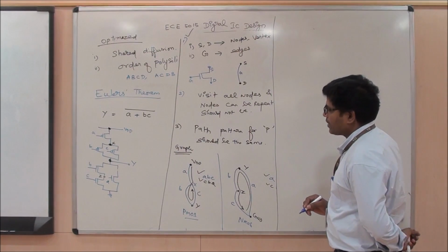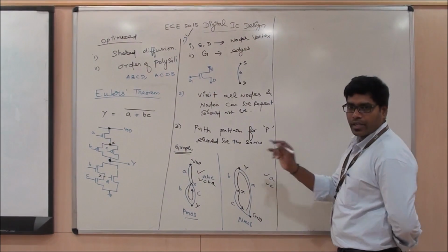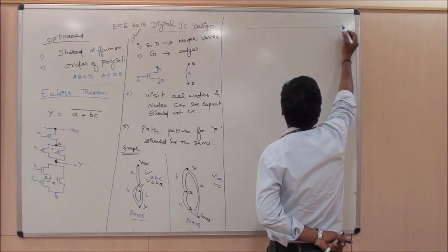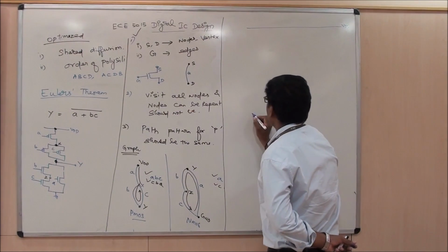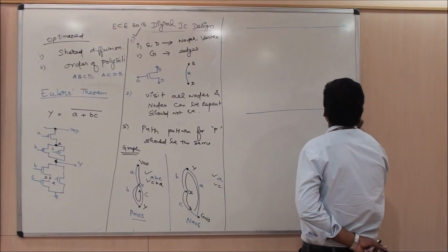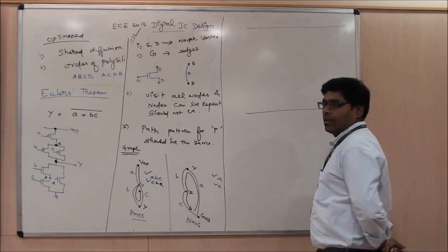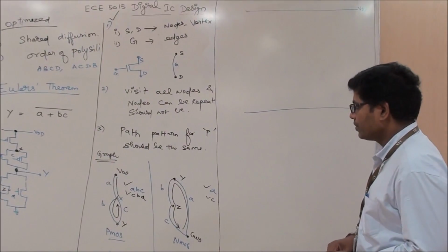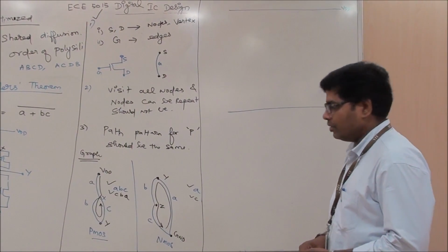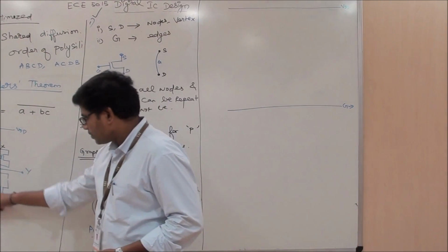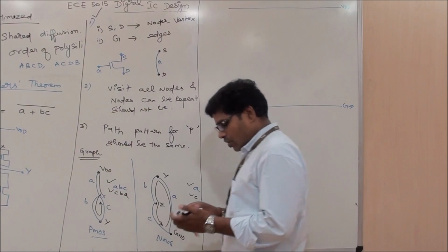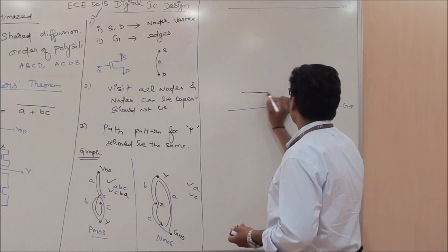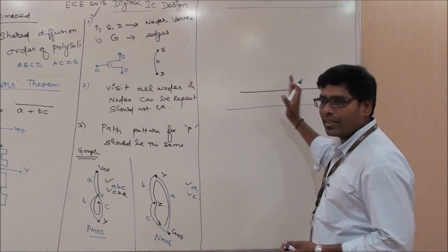So what we have decided is, for any stick diagram, you are supposed to have two metal layers. At the top you have VDD. This becomes mandatory. You can better draw it for all the stick diagrams. So two power lines I have drawn. Now the next thing is, for the whole NMOS network, I am using a single N diffusion. Remember, I am not breaking that N diffusion.